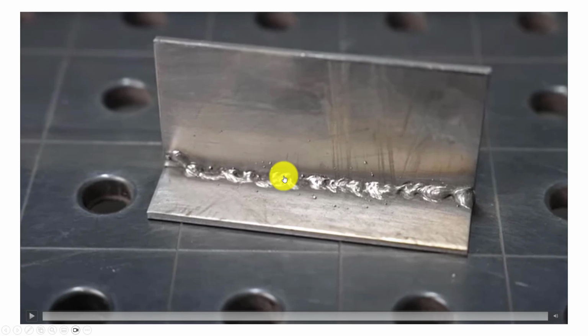Now then, I've mentioned a little bit about the heat, and the welder can see something. This is where we've captured some video for you and leveraged some other people's stuff here, where we can talk about the welds and the quality of this. So what we're going to do is come in here and watch this weld as we go across here. You can see it's kind of irregular and a lot of splatter, and it was just all over the place. And that's the part that we got. That's not a very pretty weld. That's not going to test good.